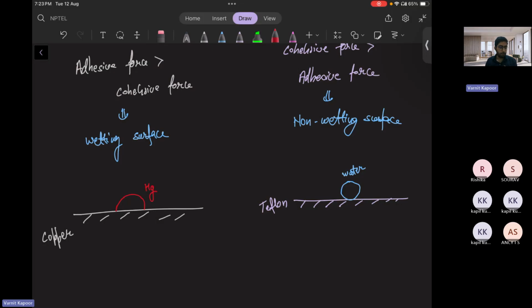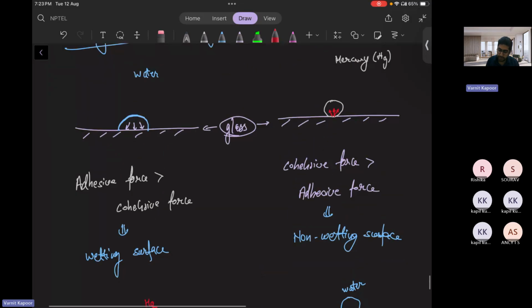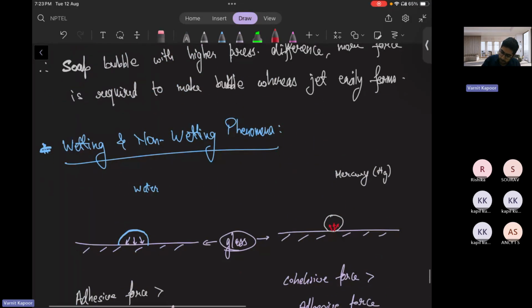Okay. Now, the point to note here is that there is an angle of contact. Angle of contact. Very important topic to understand. From here, we will go to capillarity. If you observe, if I draw a tangent from this point, the angle of contact is the angle of the tangent at the liquid interface, from inside the liquid up to that surface.